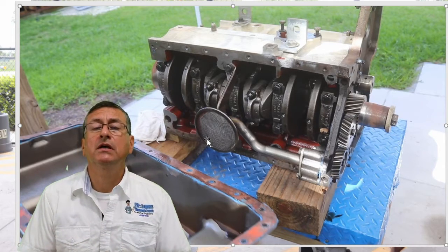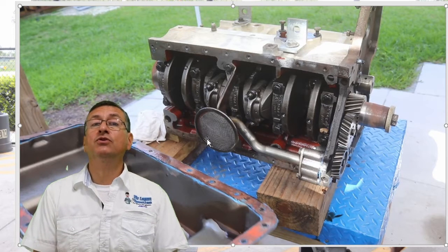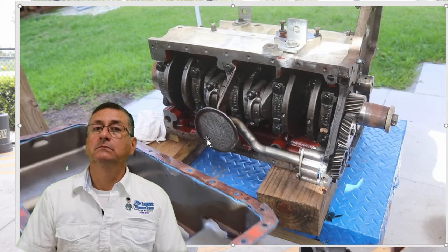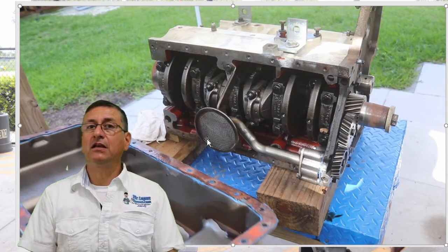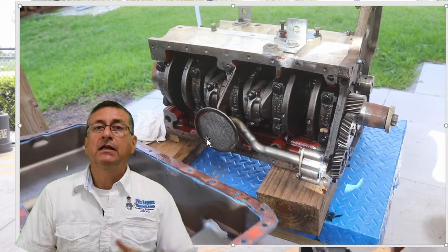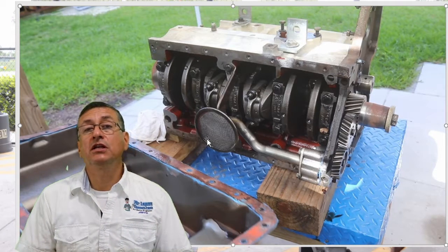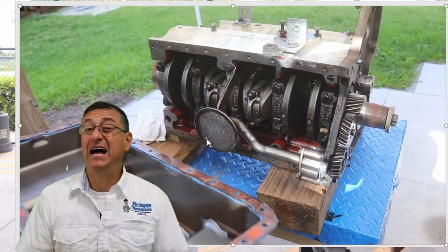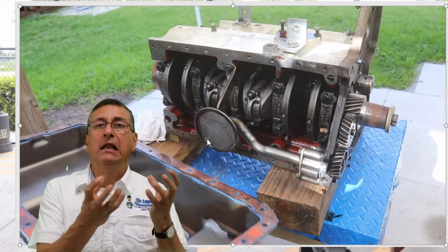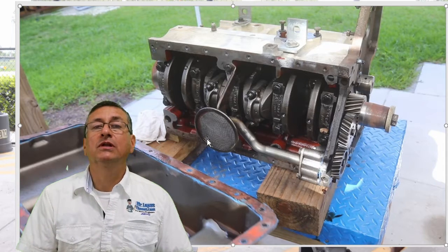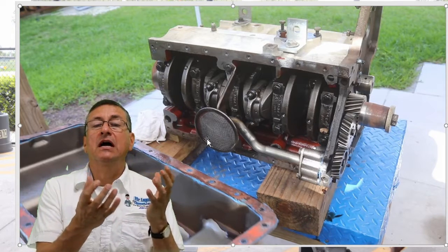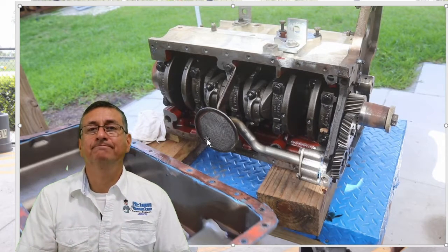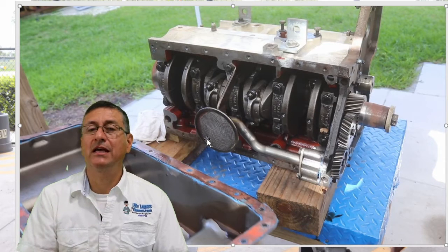One possibility is that the oil used on that engine is not the recommended oil for that engine. Another possibility is that the owner of that engine used too many additives, and the additives produce too much gel, especially at low temperatures. And those gels are deposited in the oil pan and clog the strainer. Very common. We are going to study that situation later.